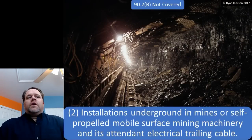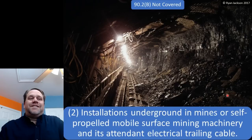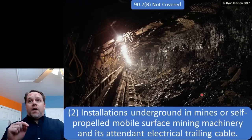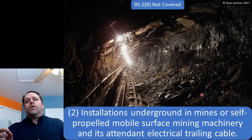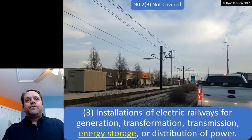Item 2, we don't cover installations that are underground in mines or self-propelled mobile surface mining machinery and its attendant electrical trailing cable. Easy for me to say. When you're underground in a mine, the code doesn't apply. You're in the world of MSHA. When you're above ground, the code applies.